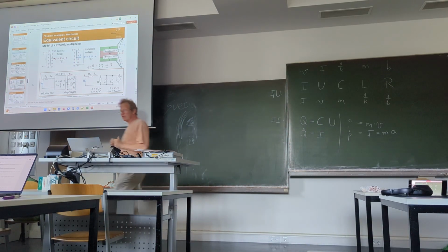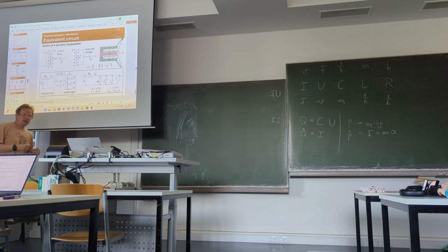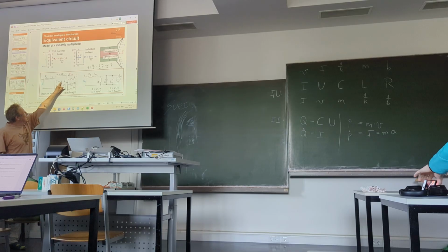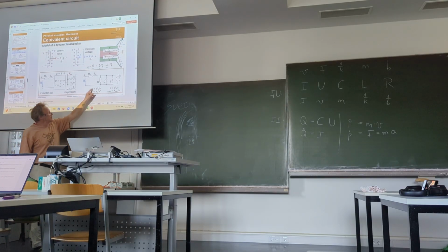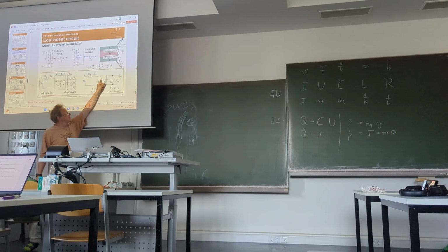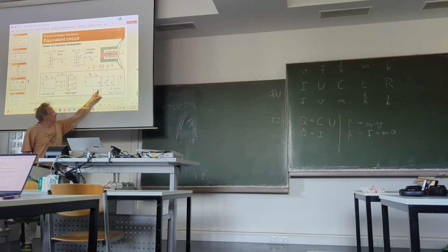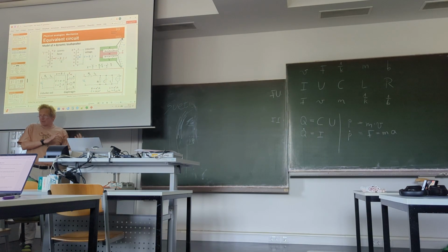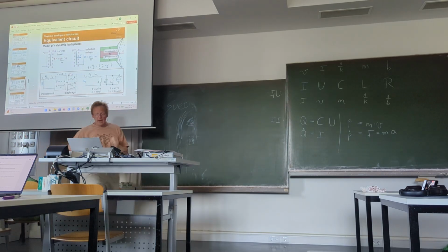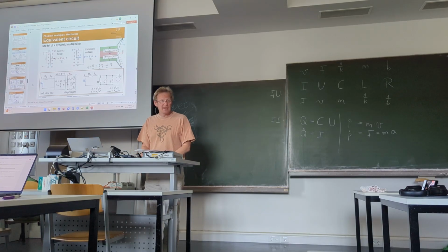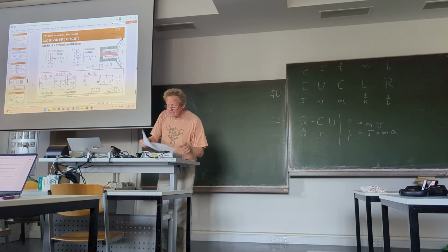Not here. Here we have a real coupling constant, which you can find in the data sheet of a loudspeaker. And this is the alpha. So we would really need to use this alpha for the calculation of the correct element values. For example, the resistance in the model here is this alpha squared divided by B, where B is the damper constant. Okay, and so on. We can measure that in reality.